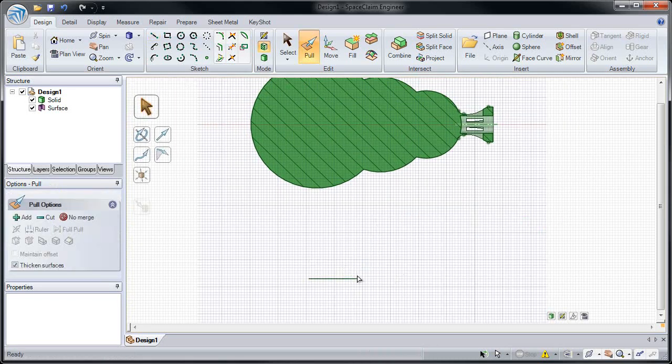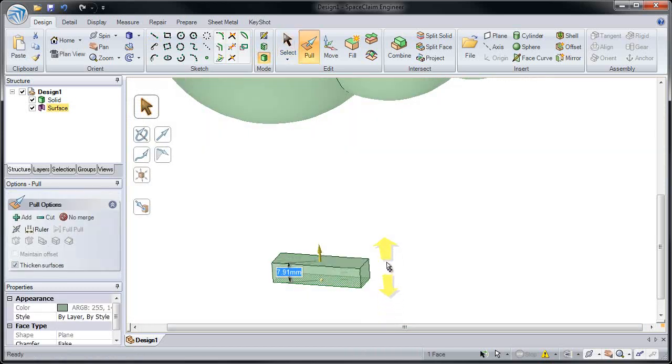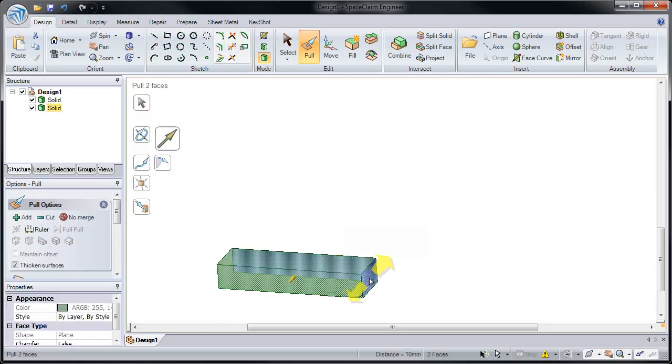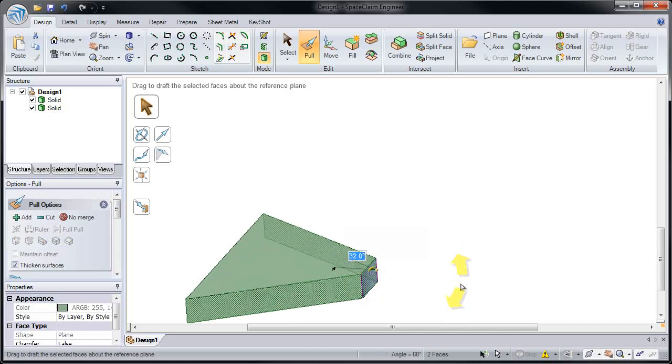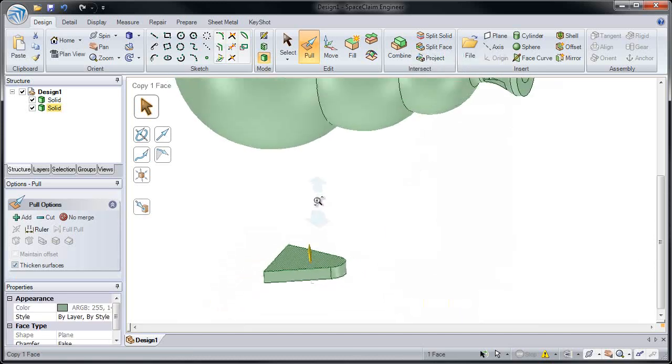We'll be able to enter it into a Z-Corp or a Stratasys machine, and print out and see the final design, and present that to our buyers. And again, SpaceClaim lets us make changes with just the Pull tool. Pull lets us draft, blend, sweep, round corners, just by directly selecting on the model.